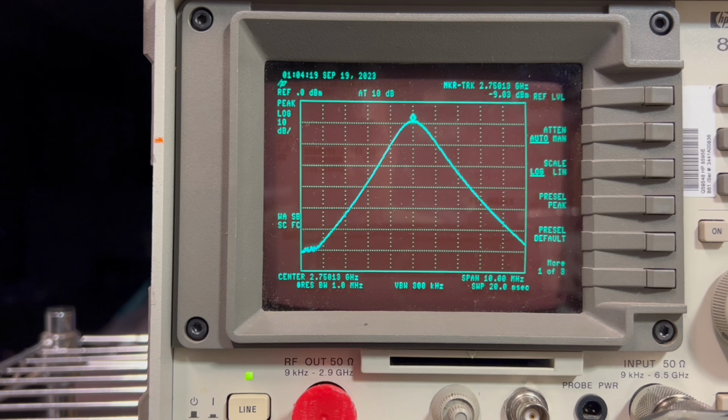So the steps for this band are 234.9 megahertz steps. Because I'm not using a real sweeper, or a synthesized sweeper, I've got to make the adjustments manually with the CW control on this one. So I have to do a little bit of math here to figure out where the next frequency range is, and I'll get that figured out, and then we'll look at the data once I complete the readings. But on the spectrum analyzer, it's easy.